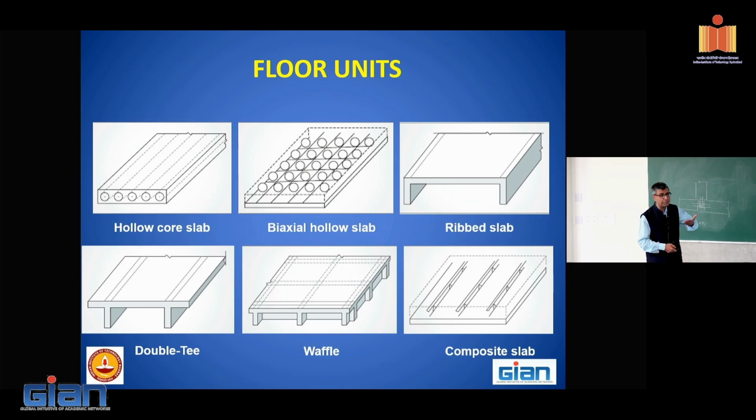Filigree means the bottom piece. Over that there are some steel trusses which are actually inserted to lift them. They are brought from the factory. And then these steel trusses also act as shear connectors with the concrete that will be cast.